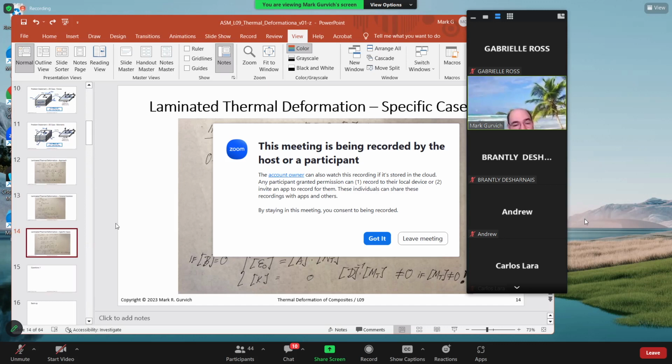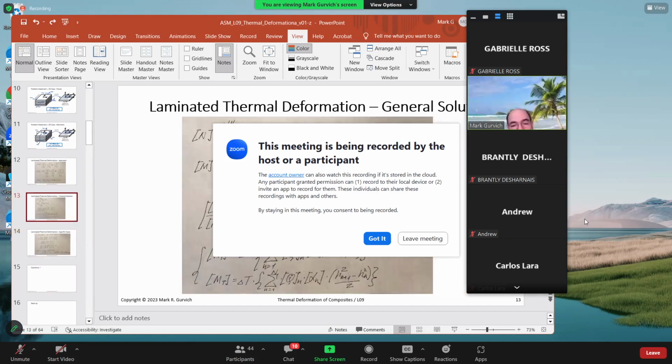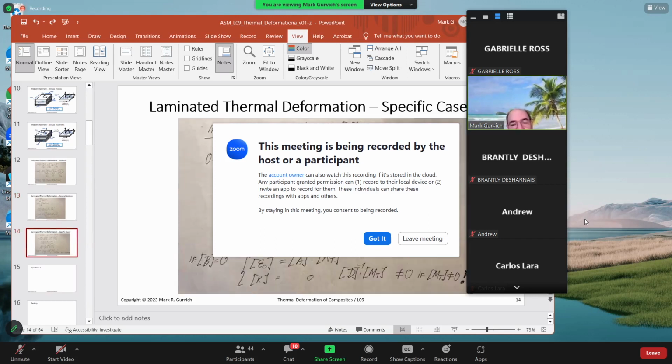So what we are doing, we consider this equation. This is the same equation, but instead of n and m, the in-plane loads and bending loads, we put 0 and 0. So n and m equal 0. So this portion is equal to 0, and 0 could also be a one-dimensional vector, like with 6 components here. So now we have this term minus this term equal to 0.